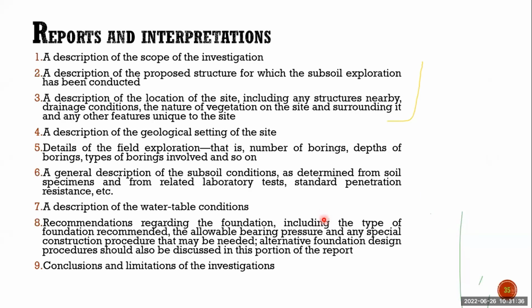Usually in the report, we describe the scope of investigation, description of the proposed structure, scope of works, and site features. We need to consider the geology and the number of borings or investigations like trial pits, depth of borings, and general description of the subsoil conditions, and in-situ testing and lab tests. We need to consider the groundwater conditions as well.